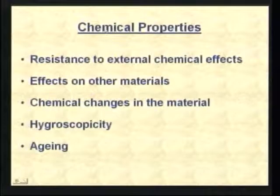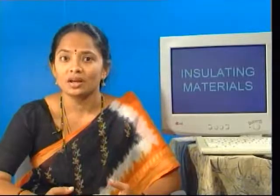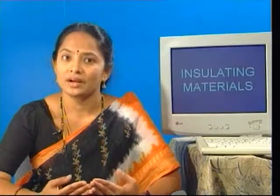The last factor is aging. Aging is the long-term effect of heat, chemical action and voltage application. These factors decide the natural life of insulators and hence of an electrical apparatus.